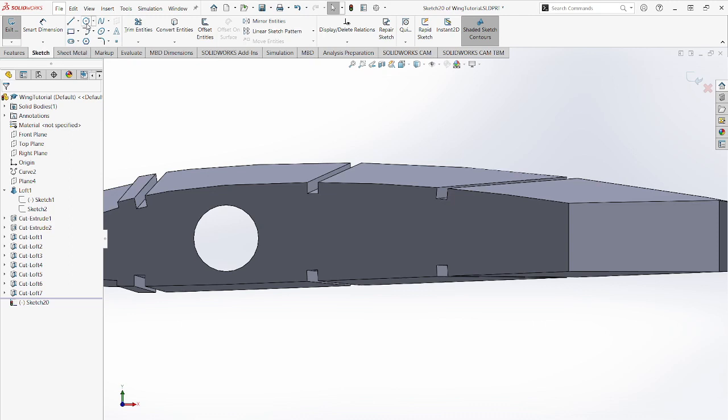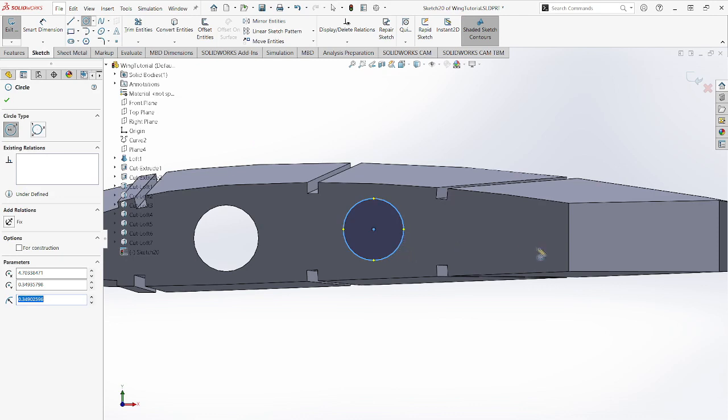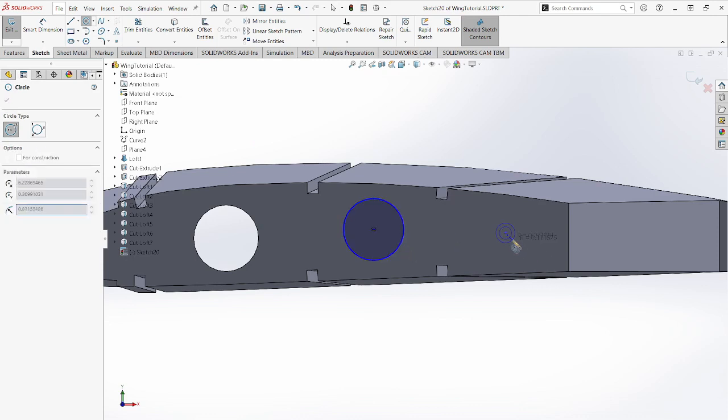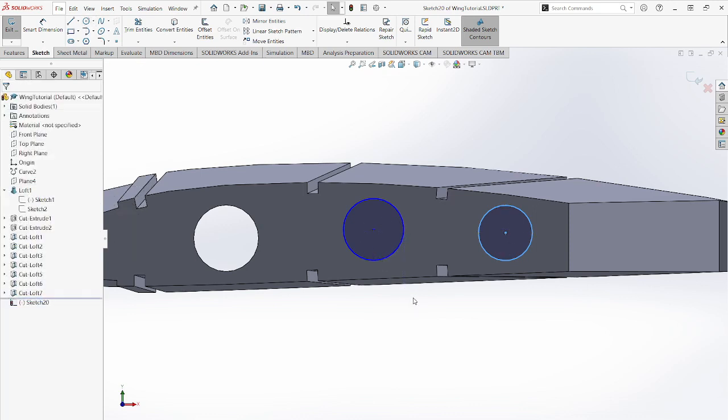And there's two ways to go about doing this. The first one is that you can just have a circle. This is easy, it's safe to do. Just put a circle there, and then in another sketch you put a circle there, loft it through the different segments, and that works perfectly fine. You remove all of this mass, and then you save a ton of weight.